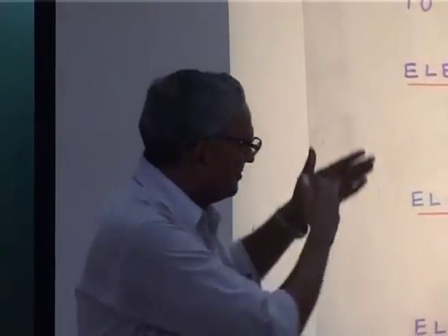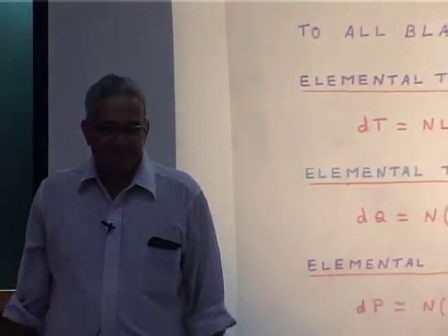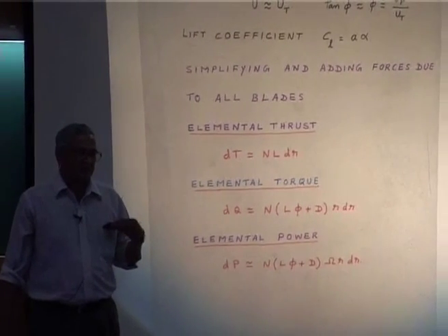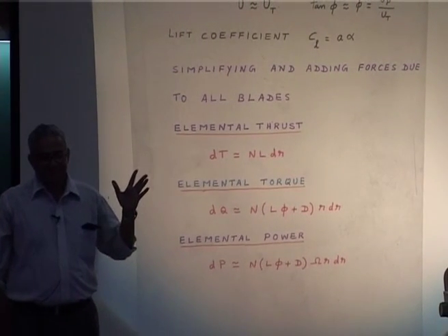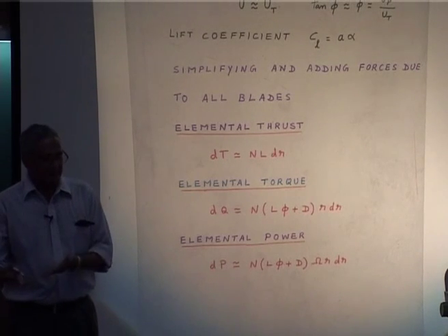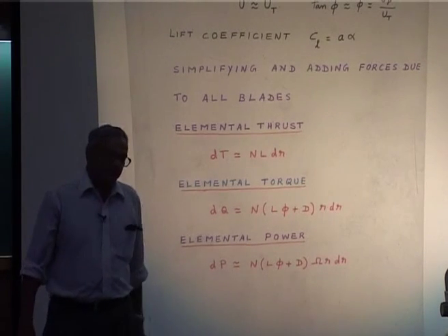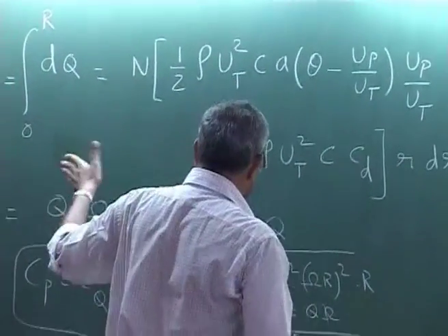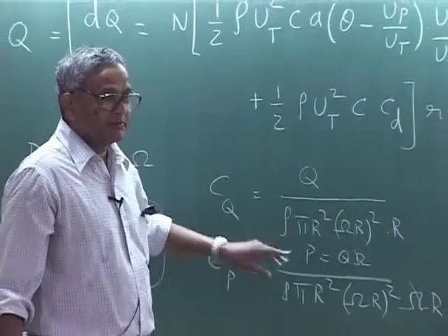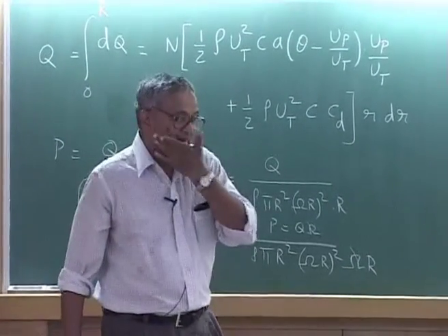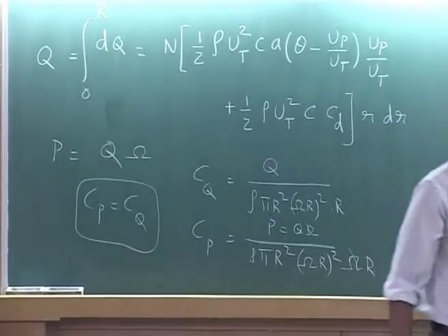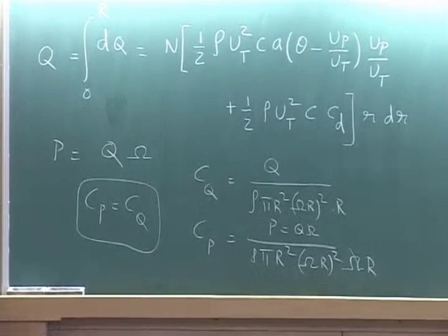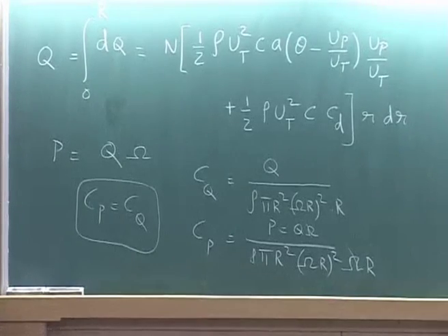That is why when we evaluate, we never use CQ, we directly go for power coefficient, okay, because Cp equals Cq. So, straight away write all the power expressions. Okay. Now, let us non-dimensionalize this. Is it clear? Okay, because power coefficient, torque coefficient both are same for rotor under constant RPM, please understand, because omega is constant, otherwise you will get an instantaneous thing.